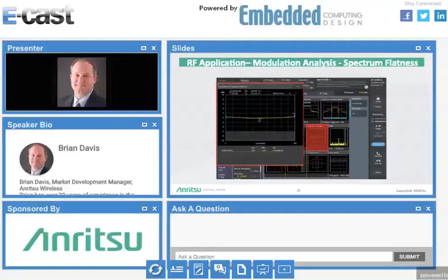The limit lines are automatically added to the in-band emissions trace. Segmentation of the incoming data stream into blocks of so many samples. So in this case, there's 500 or 600 subcarriers. So we compute the squared absolute value of the endpoints across the fast Fourier transform of each of the input blocks.